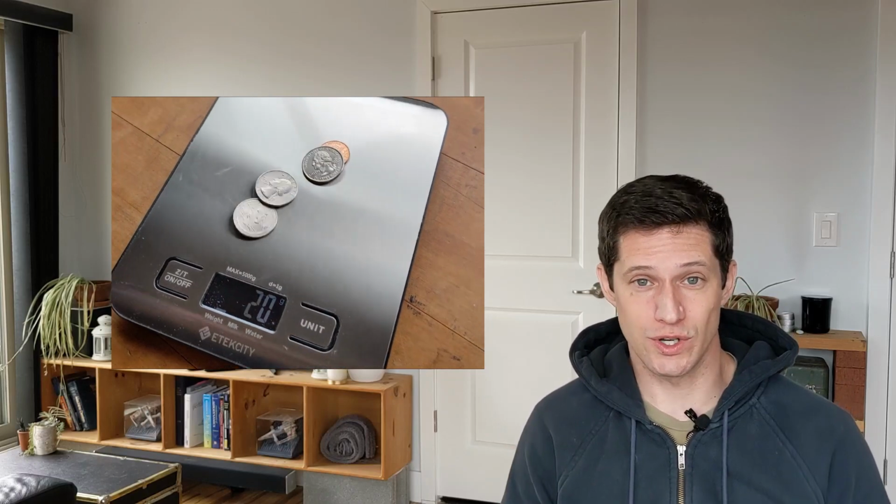But can we actually include our payload plus release mechanism and somehow only come out 20 grams heavier? 20 grams is nothing. It's literally 3/4 of a penny. Since we're allocating 50 grams to payload, that means we're going to have to fit everything he did plus release mechanism into 200 grams if we're going to stay sub 250. That's tough, but I think it's possible because even though his aircraft is super light, he didn't optimize for weight nearly as much as he could have.